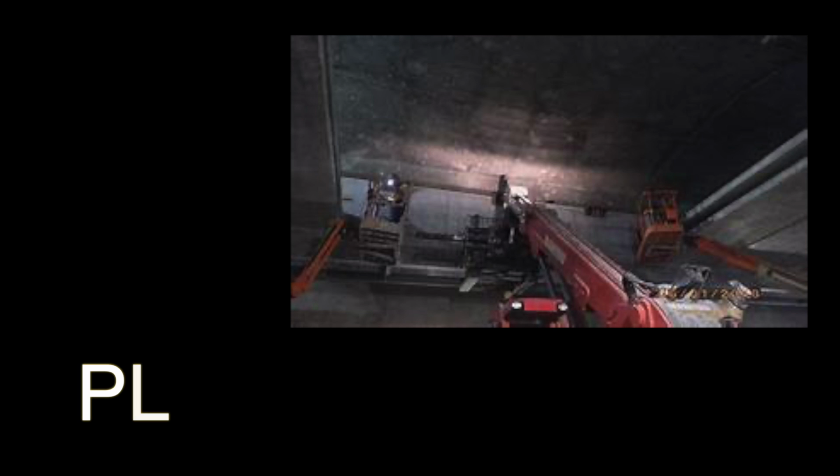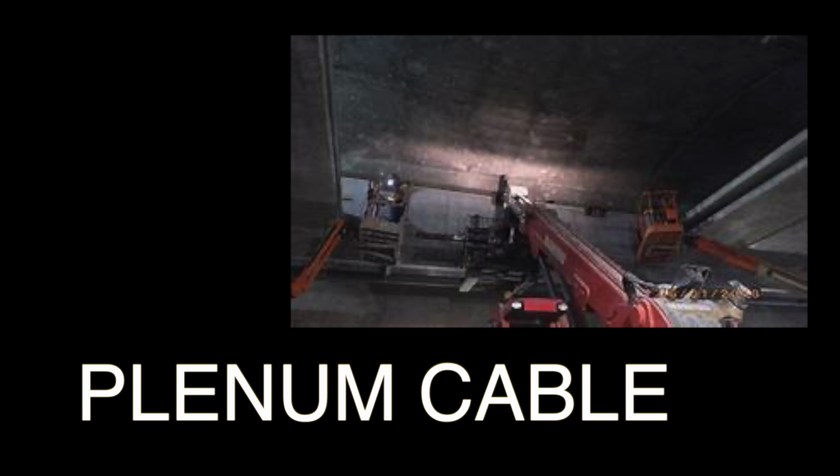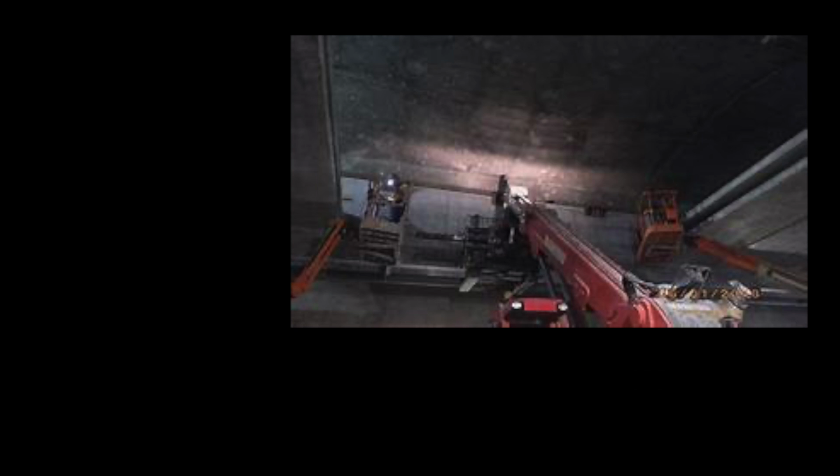So what really is plenum cable? Well, plenum cable is electrical cable that is laid in the plenum space of buildings. In the United States, plastics used in the construction of plenum cables are regulated under the National Fire Protection Association standard NFPA 90A, the standard for the installation of air conditioning and ventilation systems.